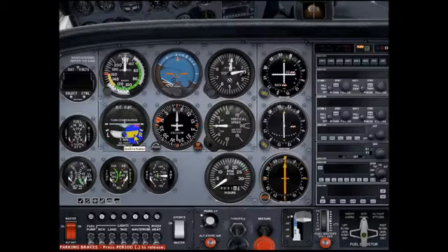If the ball slid this way, let's say, I need to back up a little bit because it depends if you're making a right or left turn. If this aircraft was making a right turn, this wing will be slightly downward. This is a miniature representation of the airplane. This wing will be upward. And a slip would be indicated when the ball is on the right side. This is called an inclinometer. And when it's in the center, that means you are in coordinated flight.